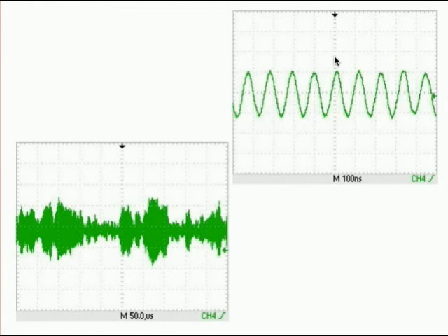So you have to have an extremely linear amplifier operated at a very low level, so the compression is minuscule, you have to have a very high noise level at the input, and you have to have a resonator with a very low Q. If you do this, it is possible to make an oscillator with an AGC control that stabilizes the output, and then you can see that the amplitude and the phase follow the same sort of law.